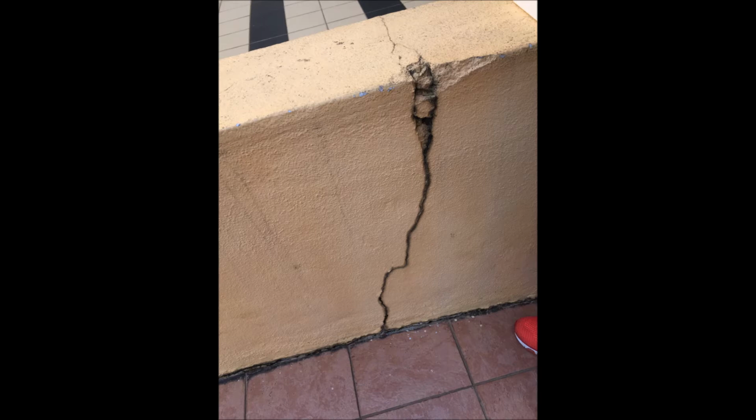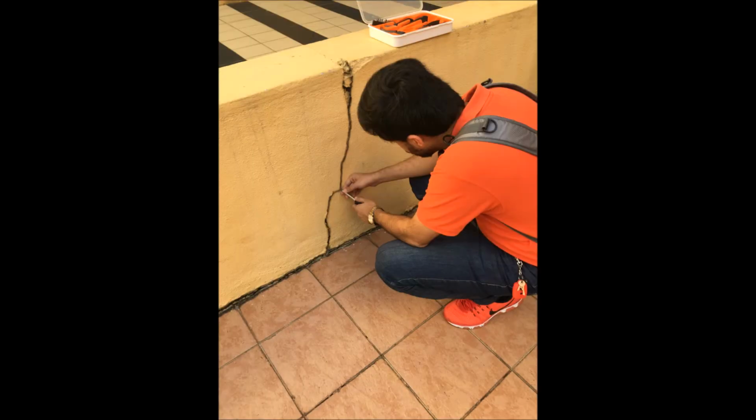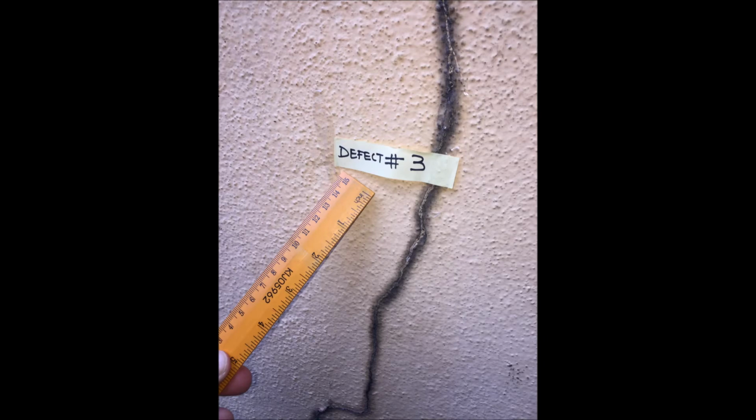The crack that you can see is at the center of the panel of cavity brickwork. The crack is the widest at the top and may narrow to a hairline crack at the bottom, especially where the brickwork does not reach the bottom of the panel. The phenomenon usually occurs where panels of brickwork are between columns, especially if the crack is diagnosed at 5 mm, which could be said to be minor or normal deformation.